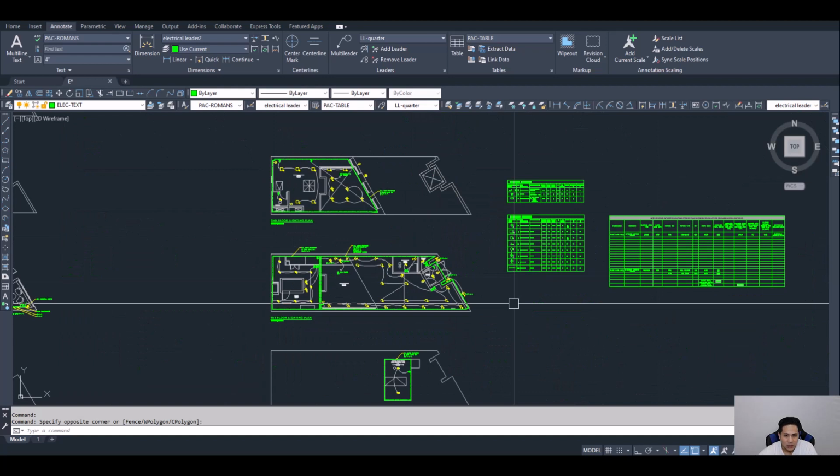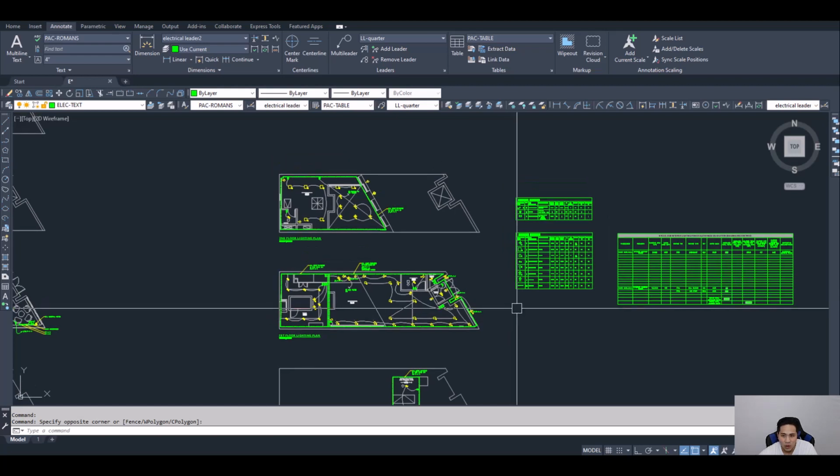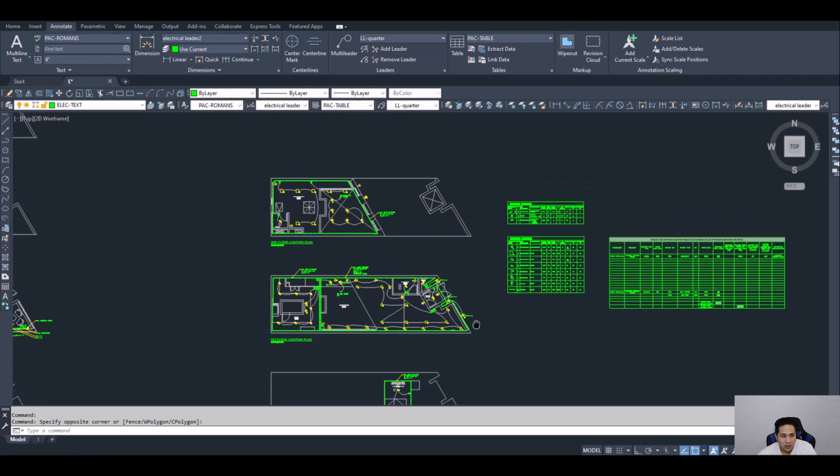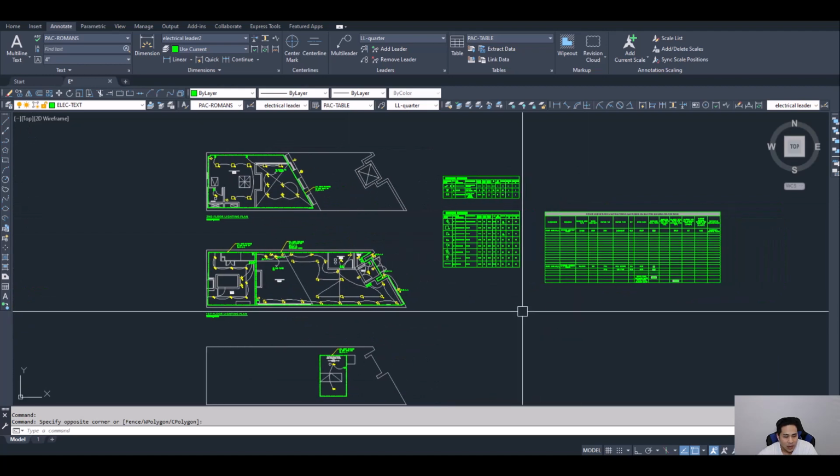Before you begin with the energy analysis, you first have to determine whether your space requires the energy analysis. In New York City, buildings that are in a historic district are exempt from the energy code. So you first have to look at the landmark map in New York City to determine whether your building falls within that historic district. If it is, the energy code would not apply for your project. In this example, let's say it does apply since it is not in a historic district. We're going to go ahead and start the energy analysis.